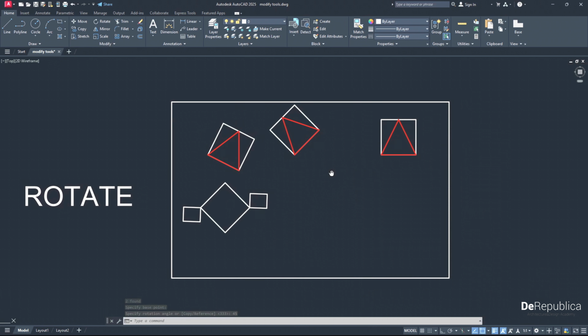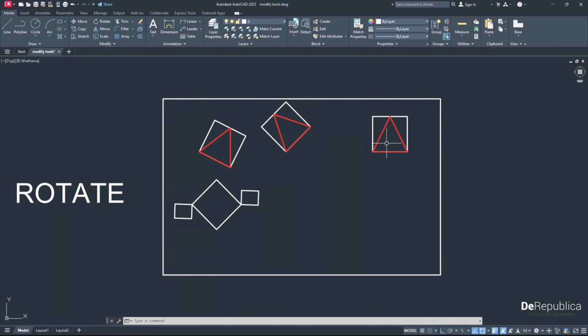Now, we can also rotate in only 90 degrees. Select the object, go to the rotate command. Now, make sure you have activated ortho mode. This icon is the ortho mode icon, or press F8 on your keyboard. Click on it until it has a light blue color around it. And now we can rotate around a point only in 90 degrees.